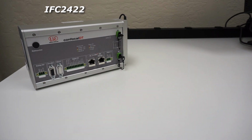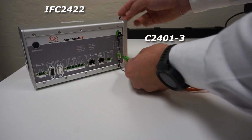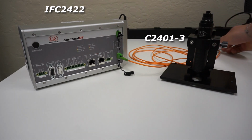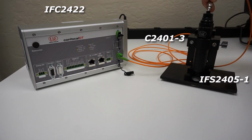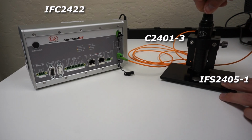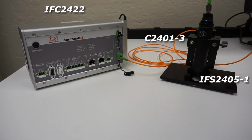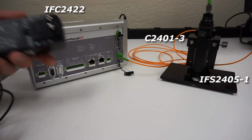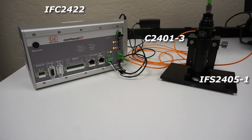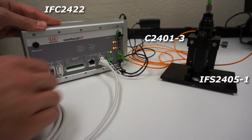So that's the controller. Then I have here the fiber optic cable, which I plug into the channel 1 connector, and on the other end I plug it into the sensor, which in this case is an IFS 2405-1 with a 1 mm measuring range. Note that there exist sensors which have the cable directly integrated. Additionally to that, I need a simple 24 volts DC power supply and also an Ethernet cable in case I want to use the Ethernet output, which I want to do in this example.